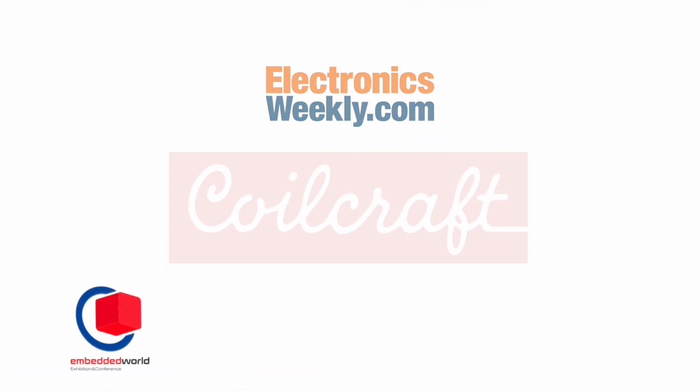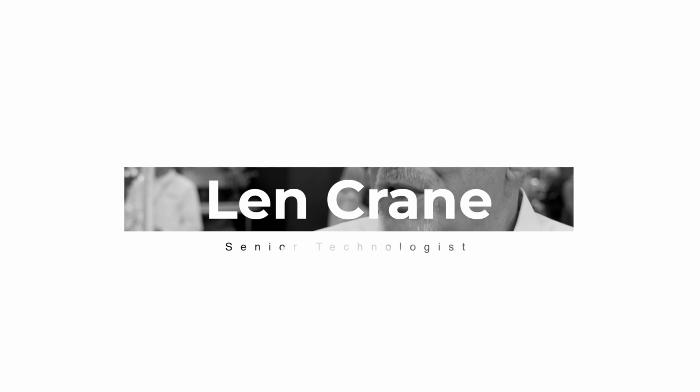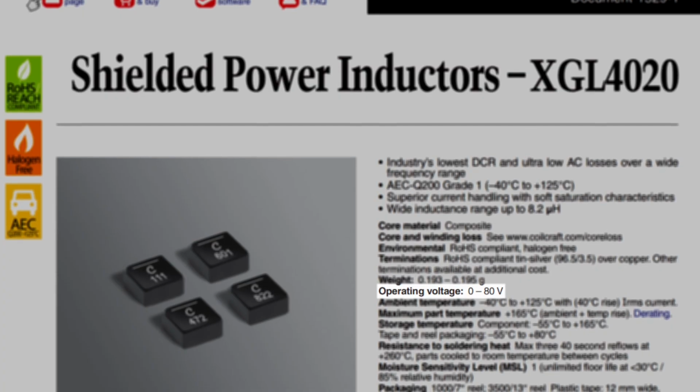Inductor data sheets haven't changed very much over decades. So the existing specifications that we've all grown up with no longer cover new situations. It's a good question about why we are even talking about specifications on such an old component, but they're used in new ways. For example, voltage ratings on inductors are really kind of a new idea. Inductors are talked about in terms of current ratings, but now we're putting voltage ratings on the inductors.